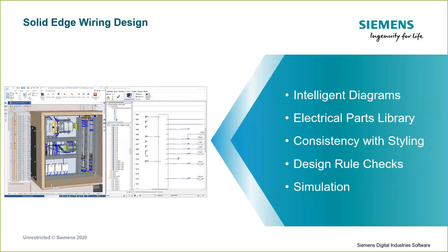You'll see that we have things like styling. What styling means is that we can set up standards so your graphics and the diagrams will look the same no matter who on the team is actually creating that wiring diagram. Font sizes, offsheet references, title blocks, all that, so we can communicate as a team and it's easy to read and follow up.